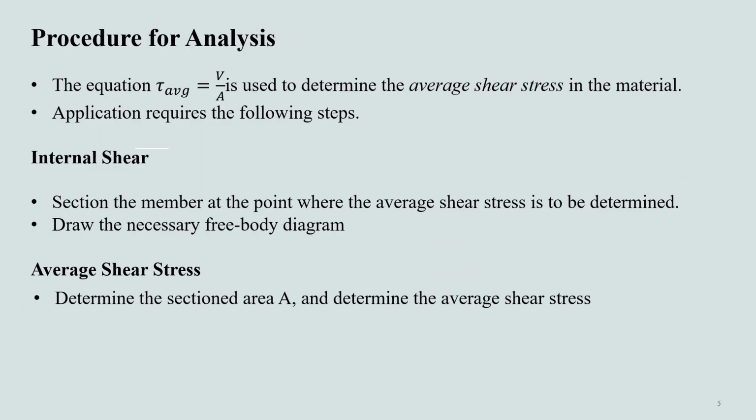How can we determine the average shear stress in any element? It basically requires two steps. First, we need to section the element at the location where the determination of average shear stress is required. Then we draw the free body diagram at that particular location.